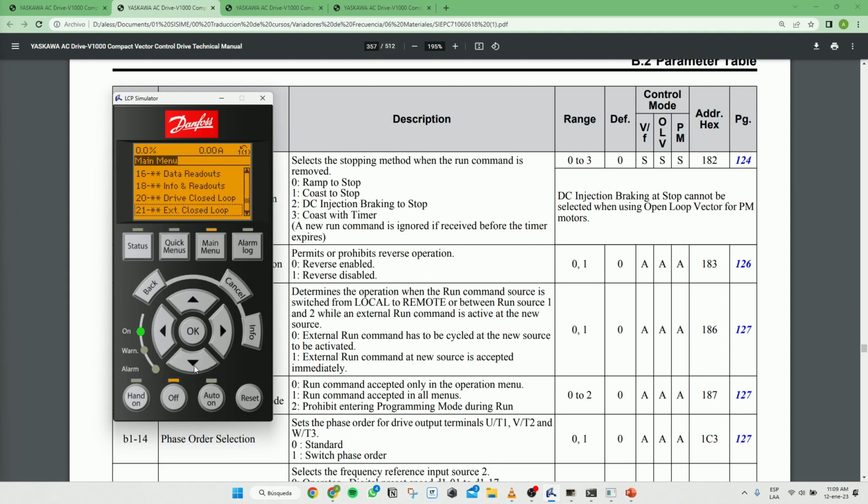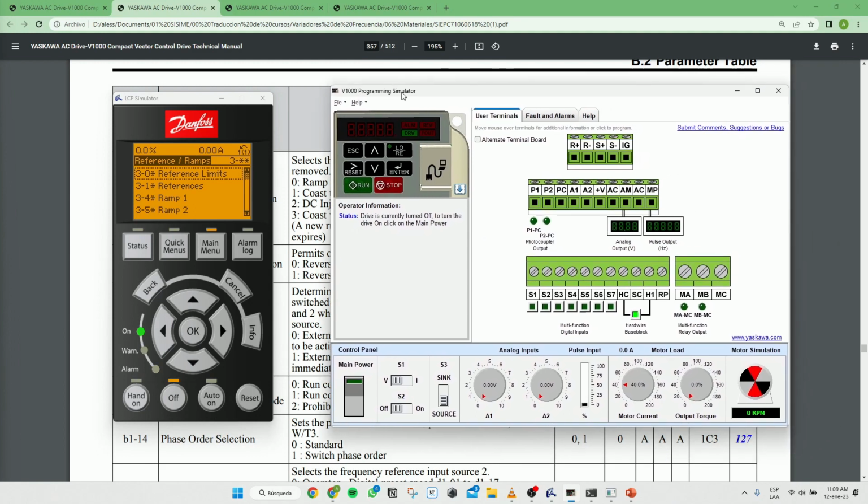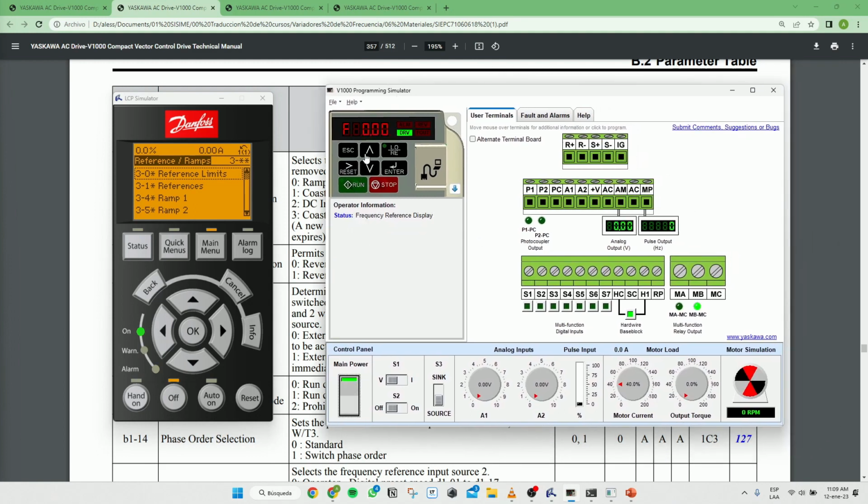And here we're going to go to our control part, when it's open loop, closed loop. Which of these options do you think sounds better for you? I think it's option number 3. So it's 3-0. Remember the Yaskawa parameters? Should be around here. Here we go. Each company is different. Each company is going to call it whatever they think is correct. So they use decimal points. So it's 3-0.